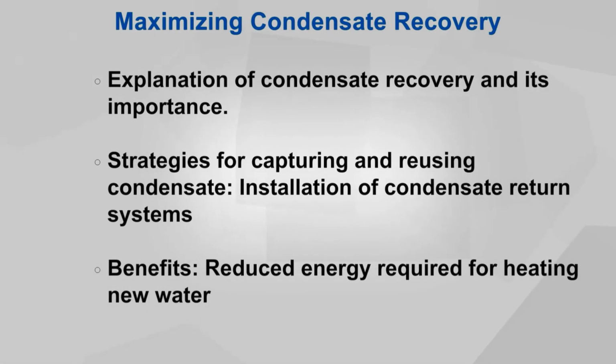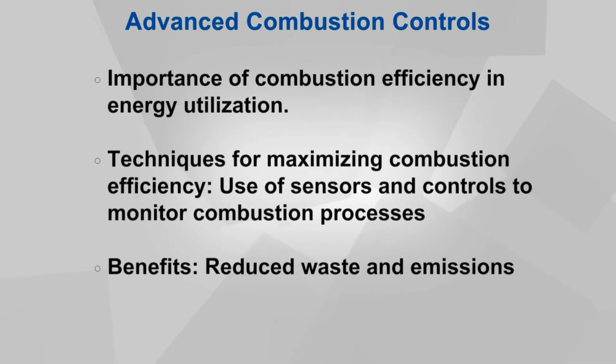Maximizing condensate recovery is another effective strategy. By capturing and reusing condensate, we can significantly reduce the energy required to heat new water. This decision can be made by process engineers. Combustion specialist prefers adopting advanced combustion controls to help maximize combustion efficiency. This ensures that fuel is burned more completely, reducing waste and emission.